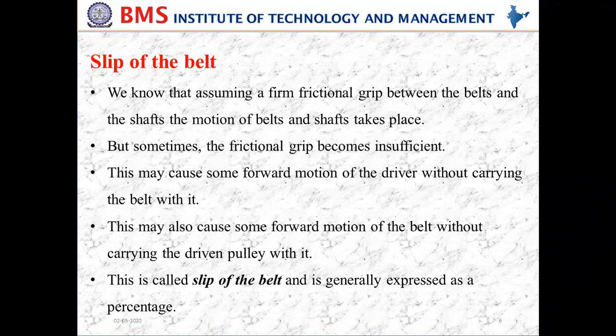between the belt and the driver pulley. Then the driver pulley moves a little without carrying the belt. That means there is a relative motion between the belt and pulley. When there is a relative motion between the belt and pulley, slippage of the belt occurs.